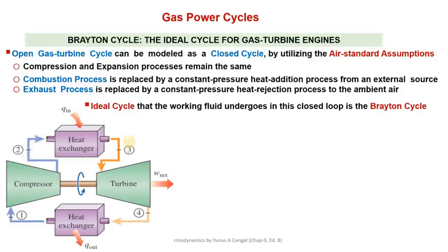But in gas turbines this temperature is very high. In steam turbines, the maximum temperature was low, but pressure was very high during this process. But here in gas turbines, the pressure is not that high compared to steam power plants, but the temperature at the entrance of the turbine is very high.